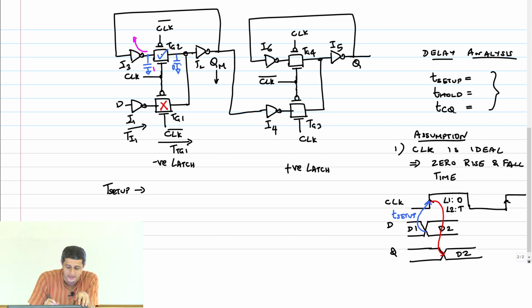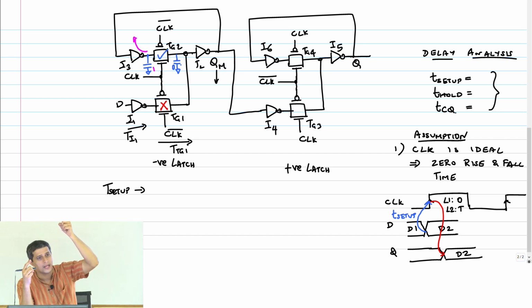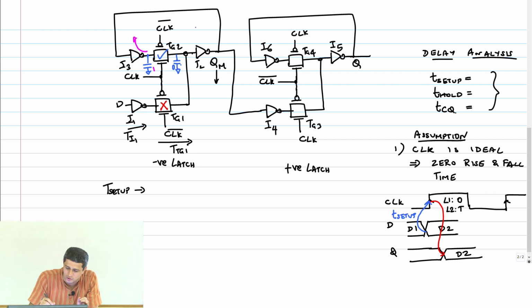It's a capacitor that's floating at ground. That means when this transmission gate TG2 turns on, and that has a logic 1 up there, it is going to charge this capacitor up. So this capacitor will start rising slowly, and instead of storing 0 or 1, it may come to some in-between value depending on where this voltage eventually settles, this node voltage X. If X is below the trip point of I2, then it will end up being a 0. If it's above the trip point, it will end up being a 1. So there is a sense of randomness there, which we don't want.